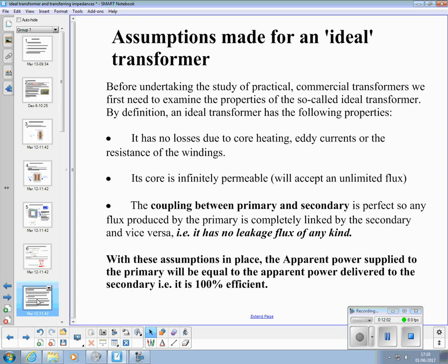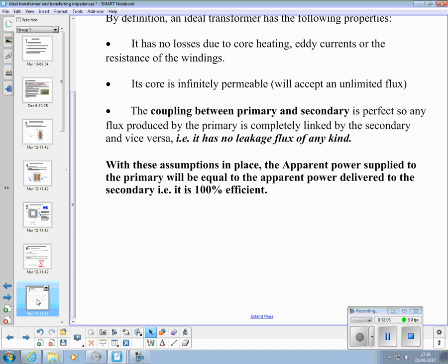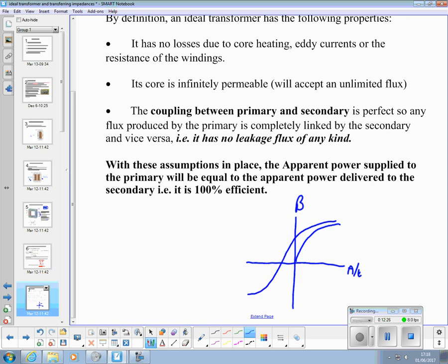And this one, infinitely permeable, what we have is, if we look at flux build up as we add current or add amp turns, there's a limit to how much flux B we can get into that core, and then as we come back down again, that goes like that, and you end up with what's called a hysteresis diagram for that core. And the wider that is, the less efficient it is, really. Because it doesn't return back to where it started and all sorts of things. So you've got losses involved in there.